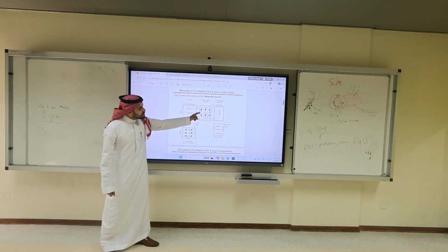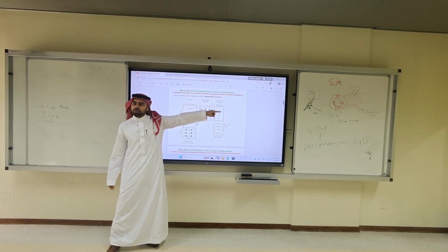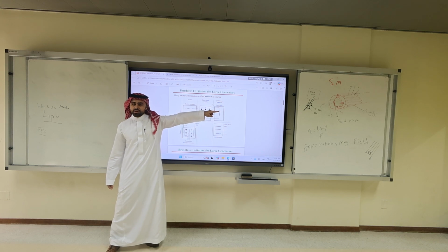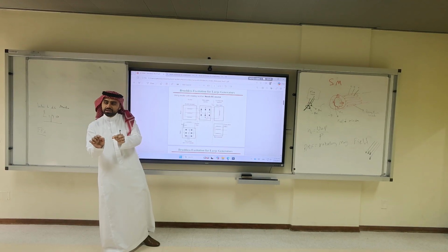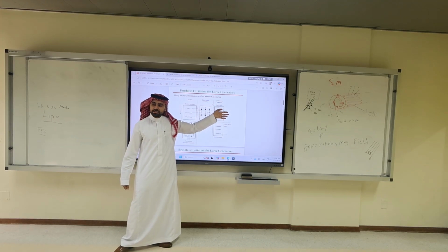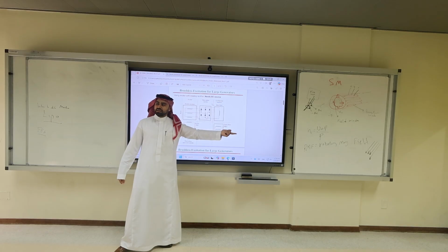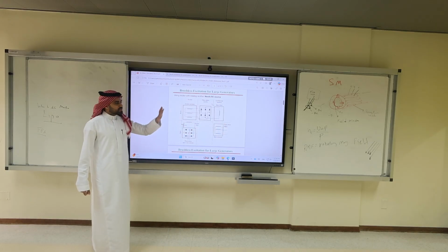Then you feed it again to the main rotor windings. So you may use some of the windings in the stator for excitation, some of the windings in the rotor, and the majority of windings you apply this constant DC current to. This way, I did not need to get an outside DC source. You see the trick? Like feedback? Not a feedback, it's a cheating method.